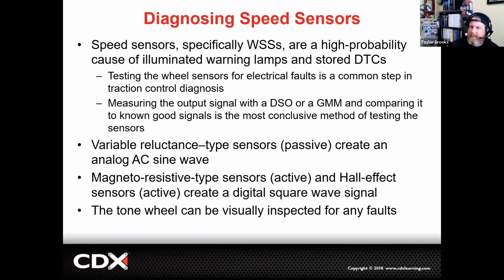Sometimes you can read scan tool data, but you usually have to have the vehicle going really slow. You cannot tell a difference between the two if there's a performance issue on the code when that's the case. But these can be used to detect vehicle slip. We talked about that in electronic limited slip differentials in chapter 11, and I go into greater detail on that. But if there's any type of variation between these, then we can have a fault that will set a diagnostic code.